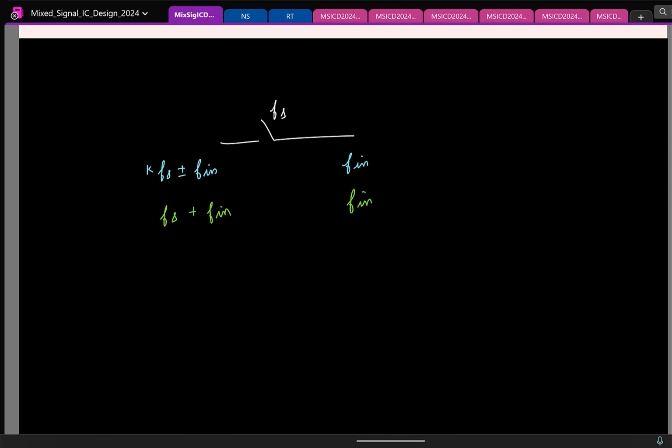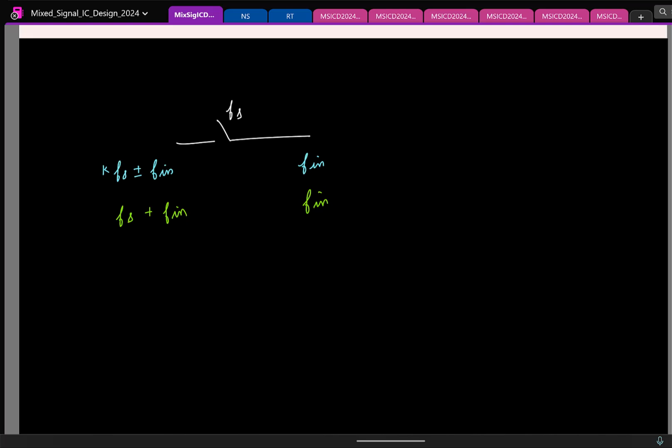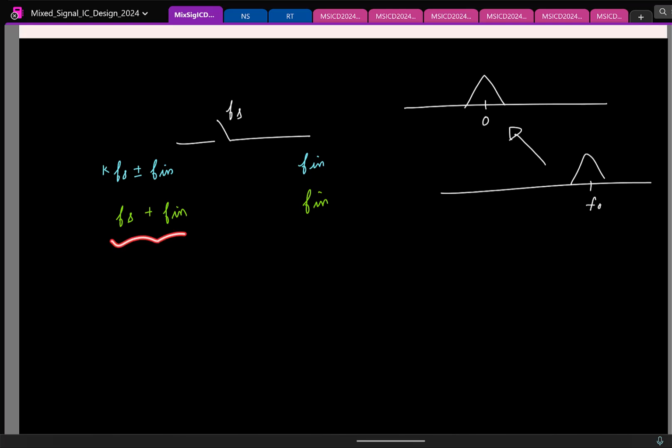Yeah, correct. I'm sure everyone is hitting at it. When we transmit a signal, you take a signal that is centered around DC. This could be what you speak, audio, your web page, whatever, and you upconvert it around a carrier frequency of Fc and transmit it. When you receive the signal, the first job is you do this, and now you see that if I have a signal like this, I sample at Fs, I get back Fin. So this mere sampling operation helps you in doing this down conversion.